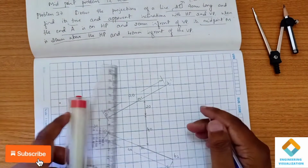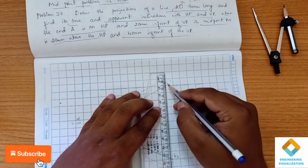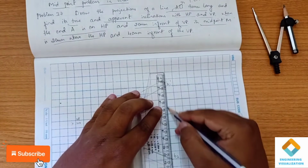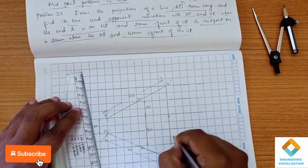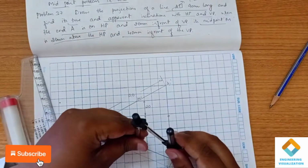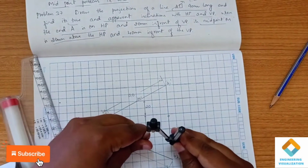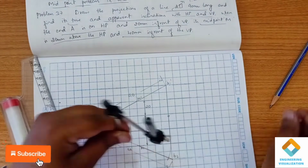So now we have to find out the upper length. So we have to project it from B1 dash till the middle point of M, where the locus of L is there, till here we have to extend. So from this end to here, measuring this length, we have to cut the arc.